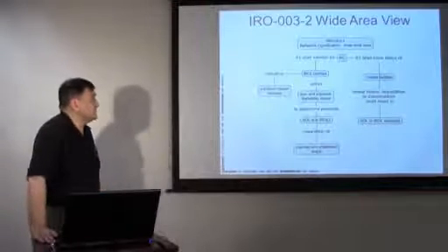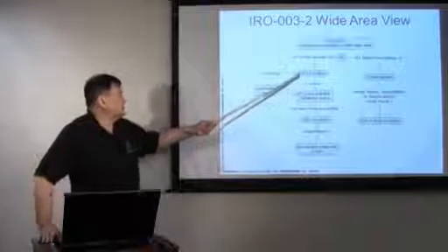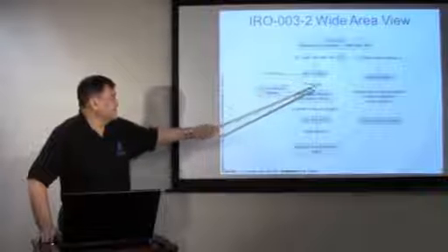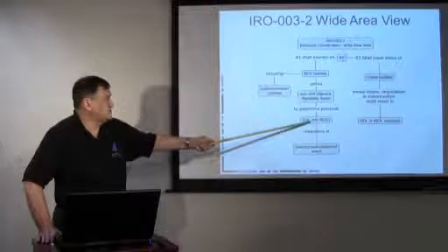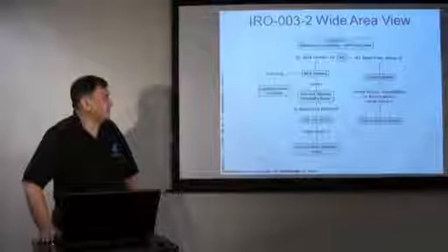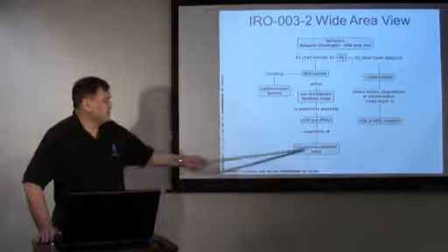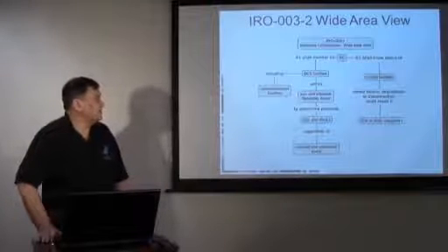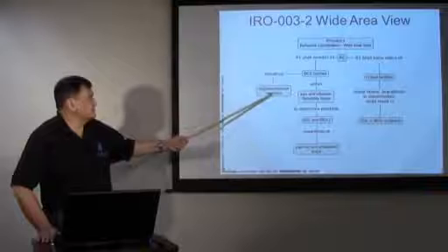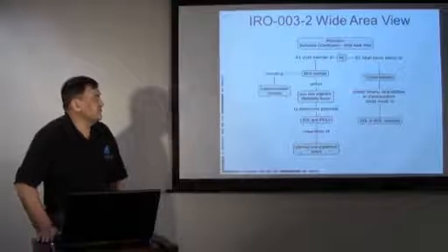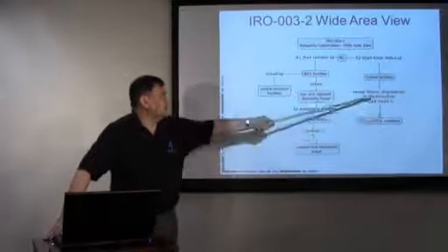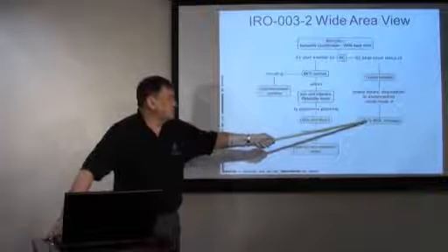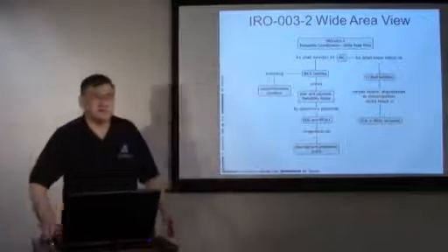So this standard says they'll monitor all the bulk electric system facilities within their own and adjacent areas, again, to determine potential SOL and IRL violations, regardless of whether it's a planned or unplanned event. They will include critical subtransmission facilities, and they will know the status of facilities where the degradation or disconnection could result in SOL or IRL violations.